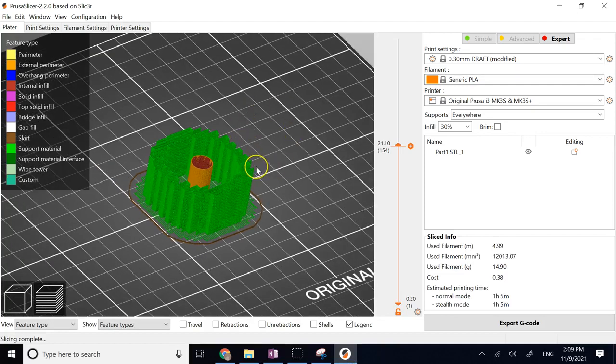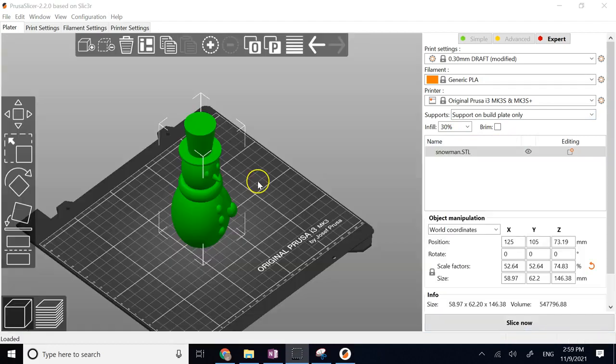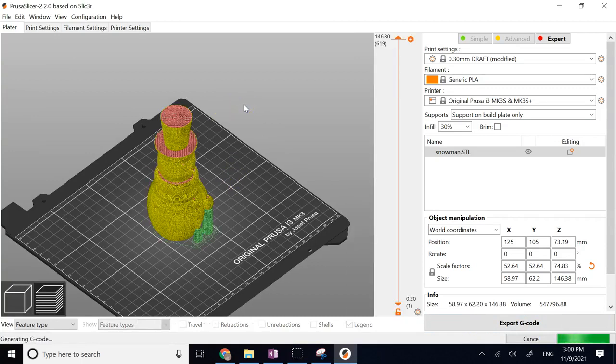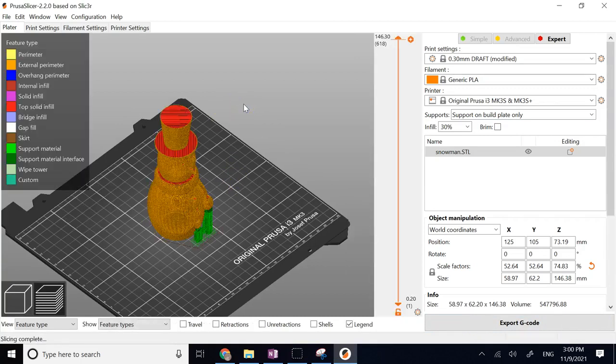And there is a bunch to this support. As I said, the transition angle of it, whether I should change my support to support everywhere or just for support enforcers or on the build plate only, correct? Or none. So here, let me show you in another model a couple of those settings, although as I said, I will have a separate video on PrusaSlicer software.